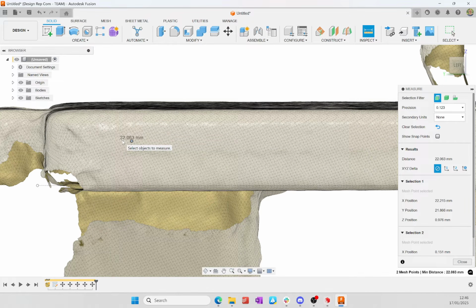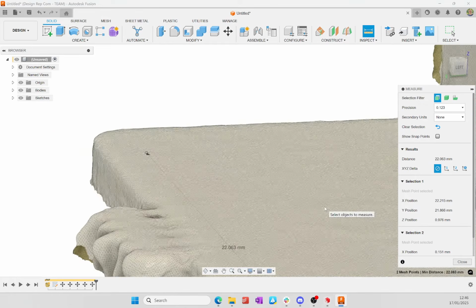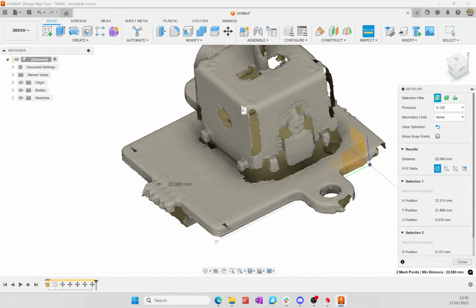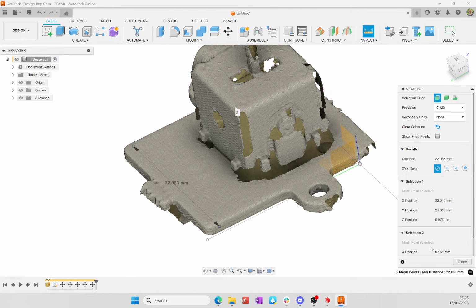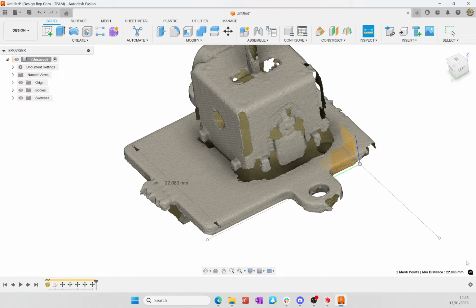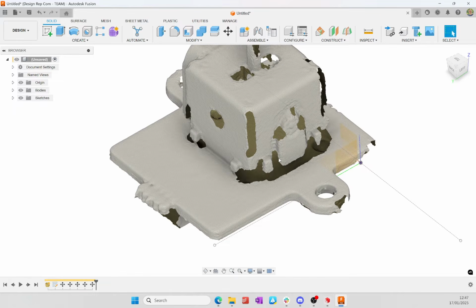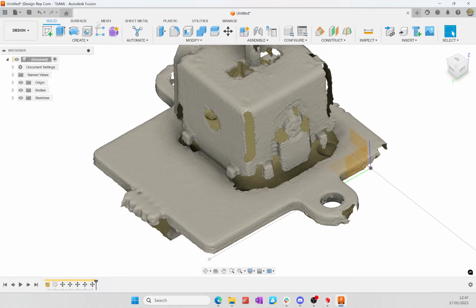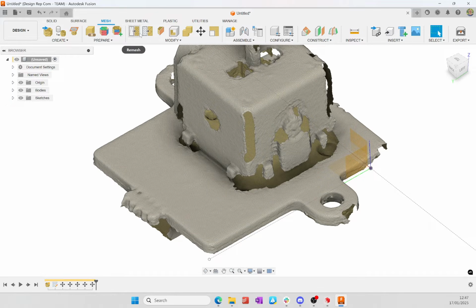I remind you that this is an overlaid scan, meaning 2 scans combined. Potentially, a single scan could yield better results. I also remind you that this scanner allows maximum resolution in the single frame or snapshot mode. Basically, it performs a single capture, and in this mode, it achieves even better results. I think this can be considered a relatively reliable tool in terms of metrology because the results are quite good, at least for these types of applications.